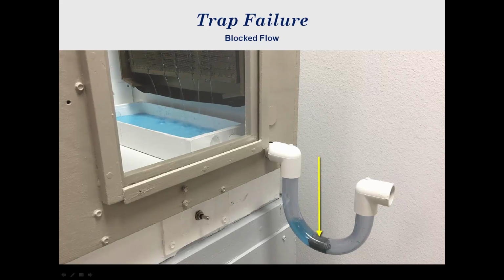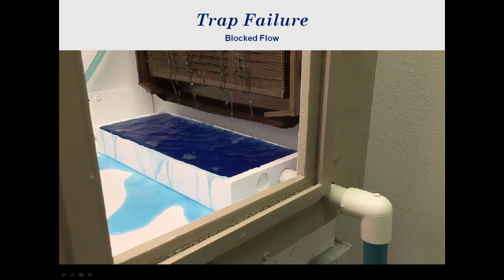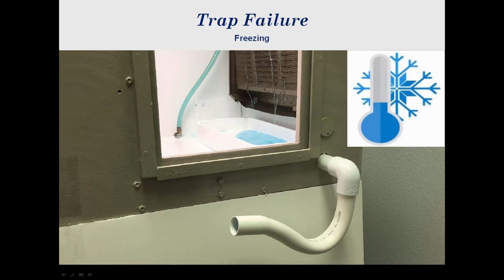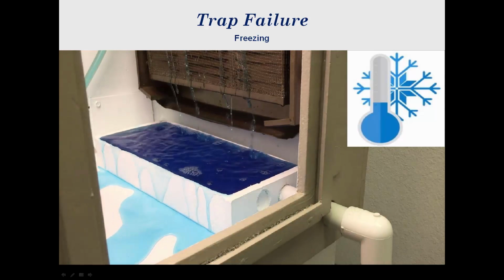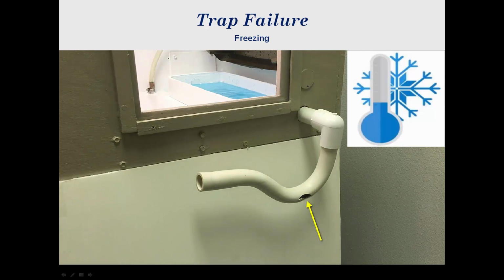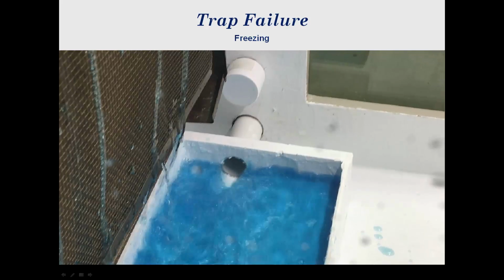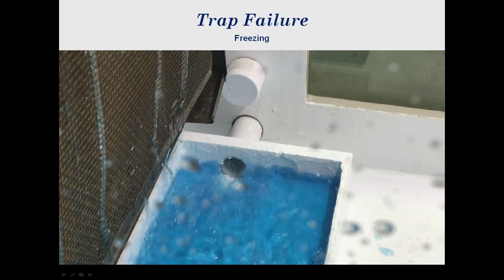Debris and algae growth frequently block traps as shown here and cause drain pan overflow, a common cause of building property damage and contamination. Condensate traps exposed to freezing temperatures can become blocked by ice, causing drain pan overflow. When freezing occurs, traps can become ruptured as depicted here and act like an empty trap, allowing air ingestion and condensate blowing during the cooling operation.